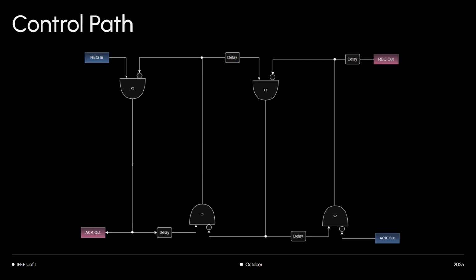Usually you take a backup of these values somewhere in a so-called shadow register. Shadow is just a fancy term given to duplicates of the same pipeline. And then you try to put that back. It gets dirty. But if you follow this strict ordering, then nothing gets dirty. It's chill. So to answer your question, when I say flush out, all the data is lost from the pipeline. Does that make sense? You had a question? You got it? Okay. Awesome.